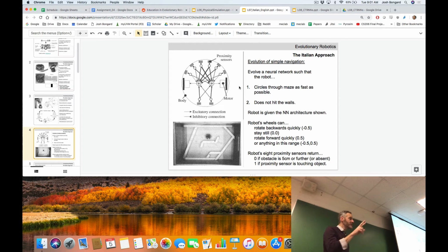So we've just looked at 2 different motor layers in 2 different robots, a wheeled robot and a legged robot, which is a reminder that the values that are arriving at the motor neuron, from the neural network's point of view, the neural network's done. It doesn't know how those numbers are evaluated. It depends on which robot we drop them into. If we drop this neural network into a robot that has a rotational hinge joint, we treat those values as desired angles. If we drop this neural network into a wheeled robot, we treat those values as desired rotations per minute, or speed of the rotation of the wheel.